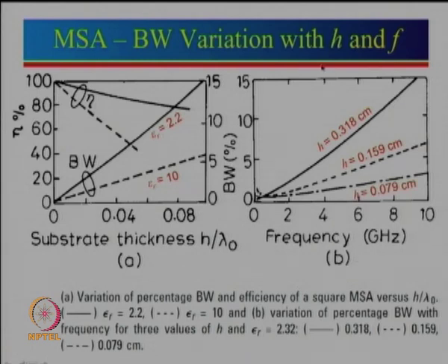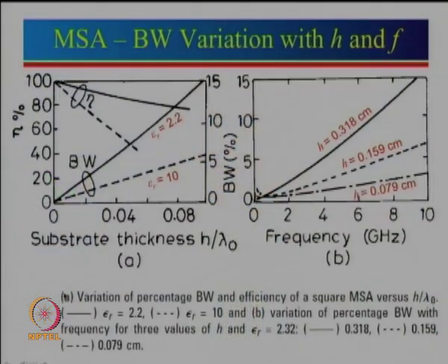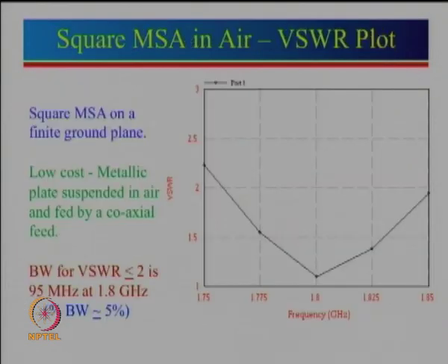Now, based on this particular information, I strongly encourage that when you need to design an antenna, please look at this curve and see what the substrate parameters should be. In fact, the substrate is a good starting point to design the antenna: given the required bandwidth, what should the substrate parameters be? So, here we have designed an antenna and given the result. I have not included the length and width; that is an exercise for you to do.